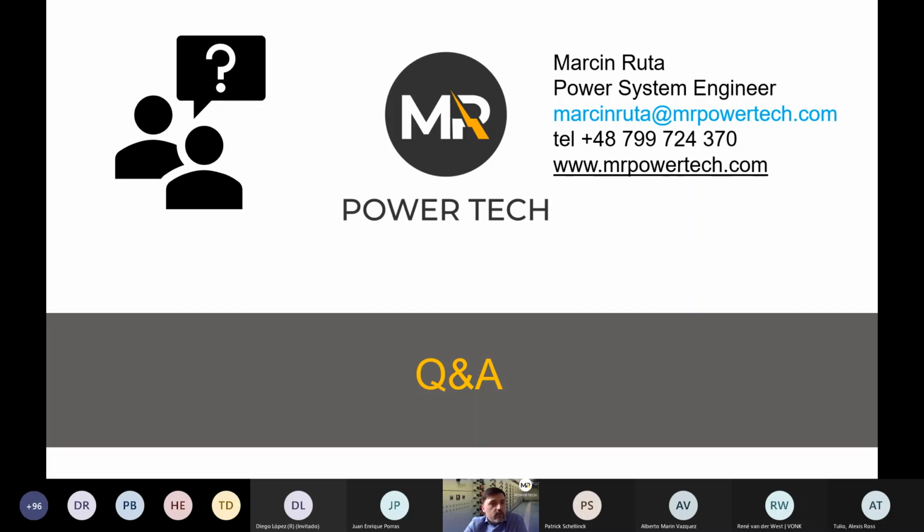And 5 years does not mean that if you change something in your system, you don't have to update. The general rule of thumb is if you modify something in your electrical installation, like you change your transformer, cables, settings or switchgear, then you have to update your arc study. If nothing happens for 5 years, then after 5 years you have to review it and check if everything is still correct and up to date, because maybe the standard changed.